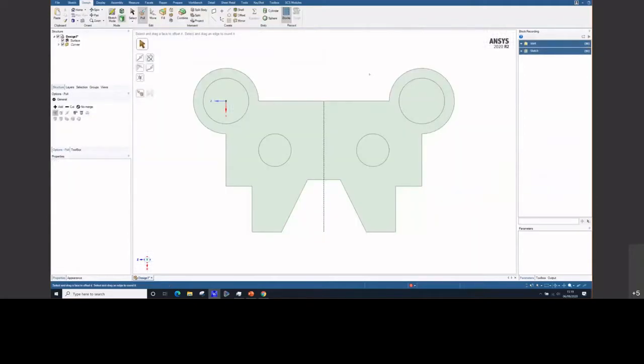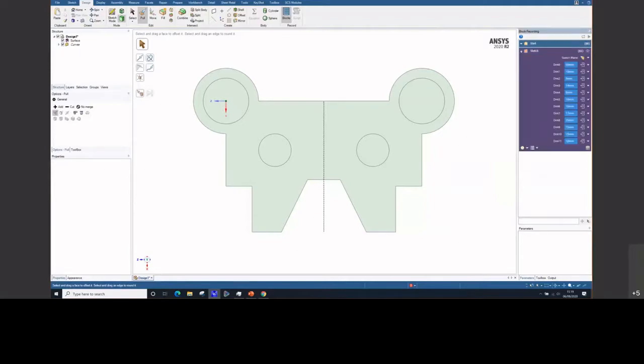it'll take you into 3D mode, as we normally would see in SpaceClaim. We get a surface now where our curves were. But if we look to the right-hand side, we've now got a block. We call that the sketch block, where we can jump back to that sketch. If we actually open it up, these are all the parameters that I've just set.